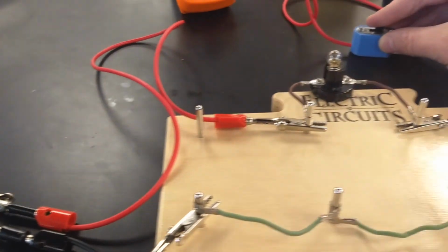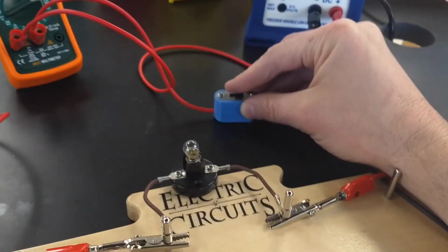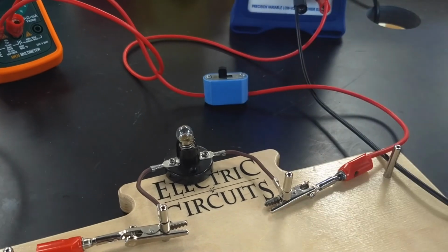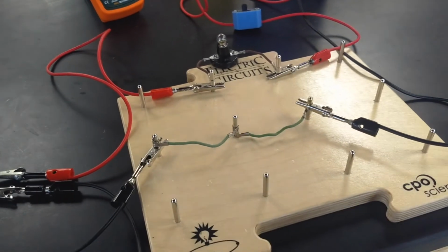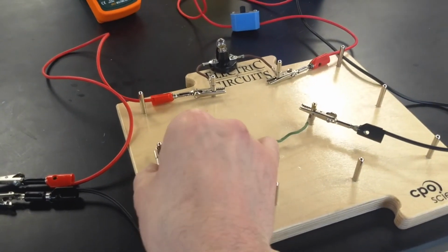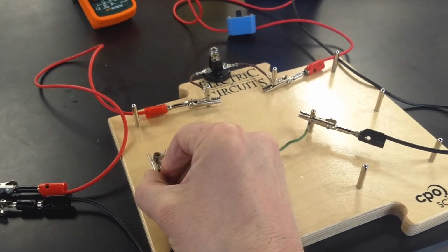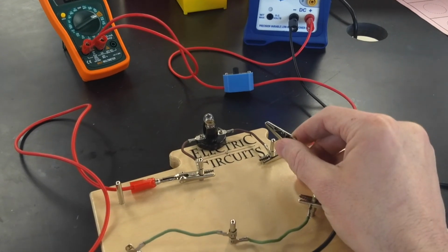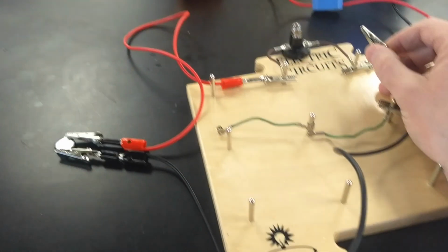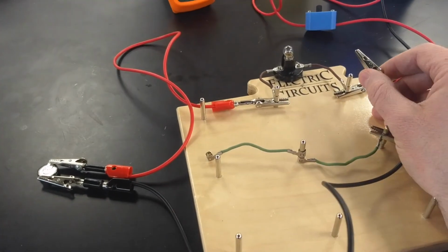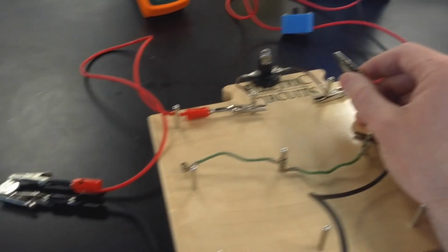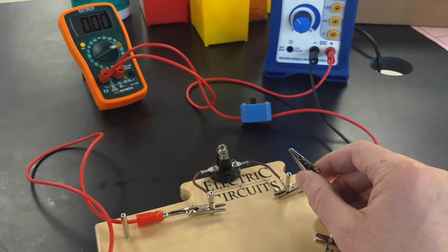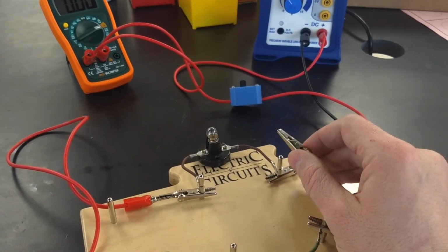And so there's a charge being separated in there that's storing energy in the form of electric field. So if I were to disconnect this circuit and then take my capacitor and wire it up across my light bulb, I should be able to discharge the capacitor. It stored energy, and that energy can be used to do something. Now, it doesn't store a huge amount of energy, and the light bulb consumes a lot, relatively speaking.